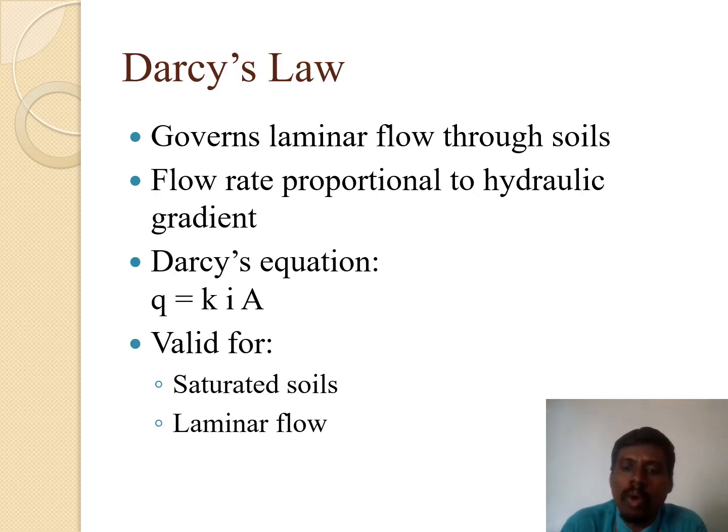The next thing is Darcy's law. It is an important one. Whenever we derive permeability questions, first we have to know about Darcy's law. Darcy's law is only applicable for laminar flow and also in saturated soil. Laminar flow means a uniform velocity of water flow. Actually the laminar flow is assumed for the flow of water inside the soil particles.